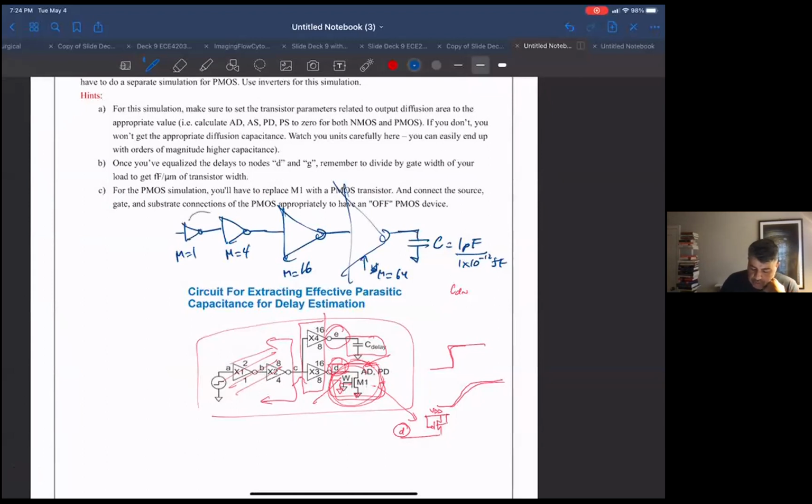You get the most efficiency in terms of total delay when these sizes are going up by a factor of 2.5 to 5. It's not exact, and we went through it pretty quick and didn't really prove it, but that's how it goes.